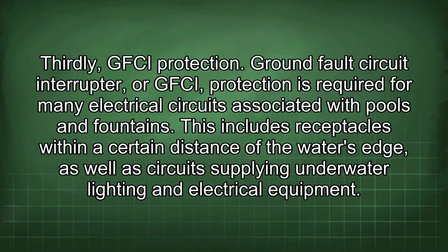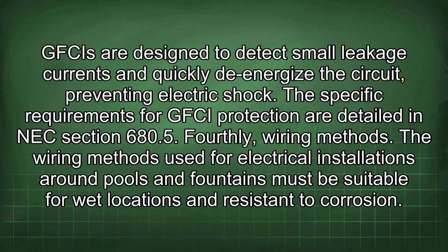Thirdly, GFCI protection. Ground fault circuit interrupter, or GFCI, protection is required for many electrical circuits associated with pools and fountains. This includes receptacles within a certain distance of the water's edge, as well as circuits supplying underwater lighting and electrical equipment. GFCIs are designed to detect small leakage currents and quickly de-energize the circuit, preventing electric shock. The specific requirements for GFCI protection are detailed in NEC Section 680.5.